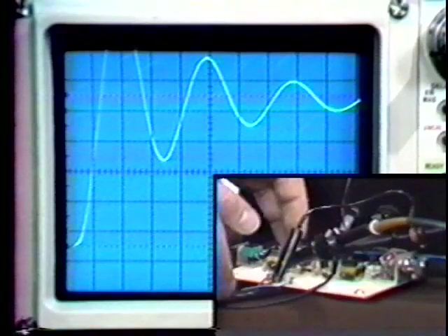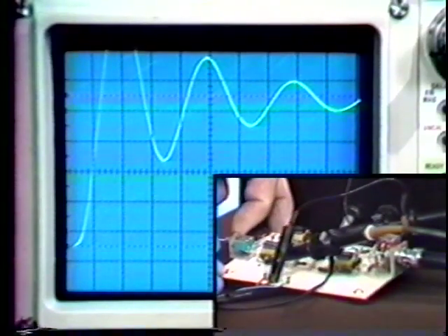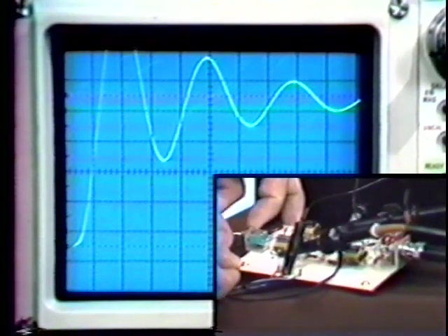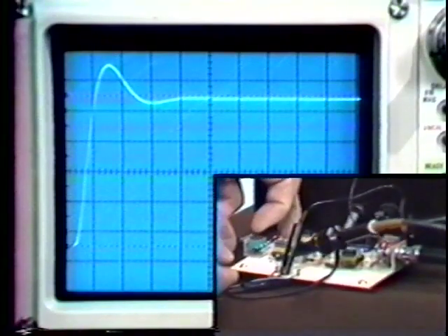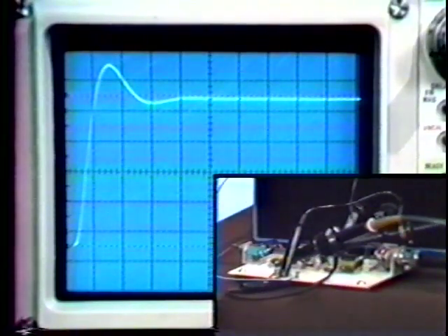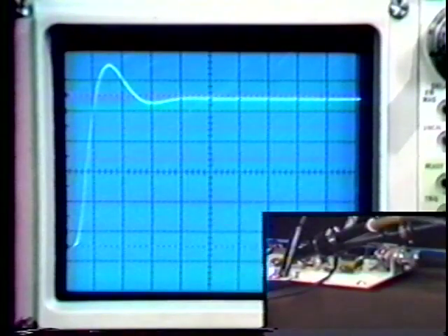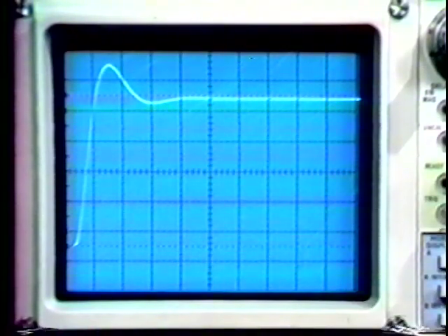So let me, as I say, do something which is really prohibited by my original problem statement, but I include it in the experimental setup to convince you that this method really does give us very good results. There is the result of applying lead compensation in the forward path to the same A of S. So now all we've done is put a block that's the lead transfer function in the forward path.